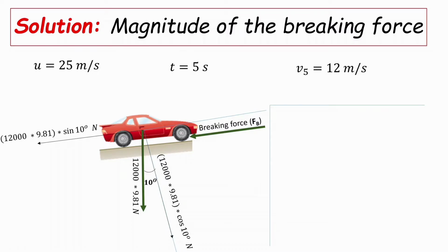So that is to say, we have two key force components that are acting against the direction of the vehicle, and we have one that is acting perpendicular to the direction of the vehicle, and that can easily be neutralized by the reactions from the road. And then we're to call in our various kinematic relations. The first one is Newton's second law that relates the summation of forces to the product of mass and acceleration. Of course, this can be suitable because we can easily get the value of acceleration from the different values of velocities and the time that is given.